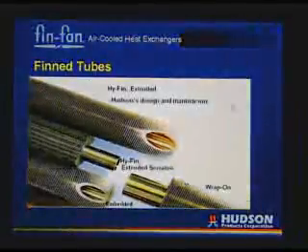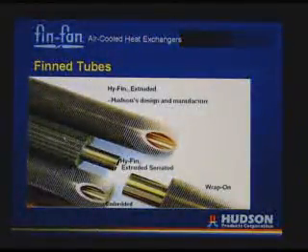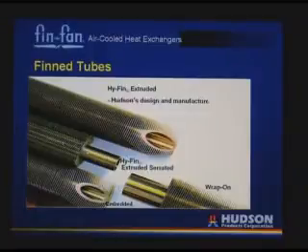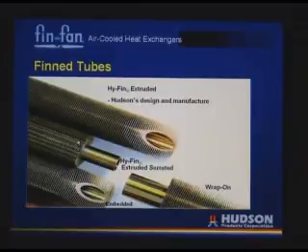This shows you other examples. This is a serrated fin, extruded serrated. This is used when you have severe heat transfer performance requirements. It is not a preferred fin because you have a much higher airside pressure drop, but for critical service where you have limited real estate and you have to make the unit work, this would be an option.